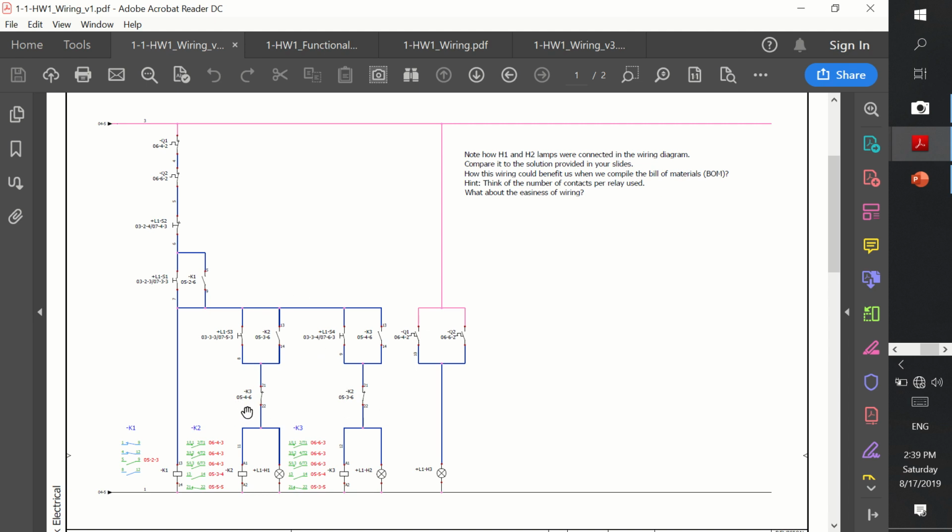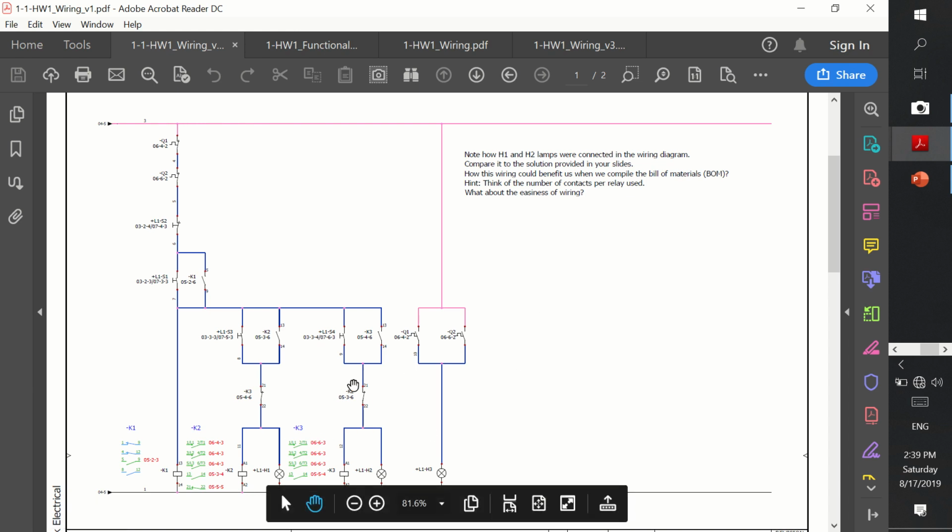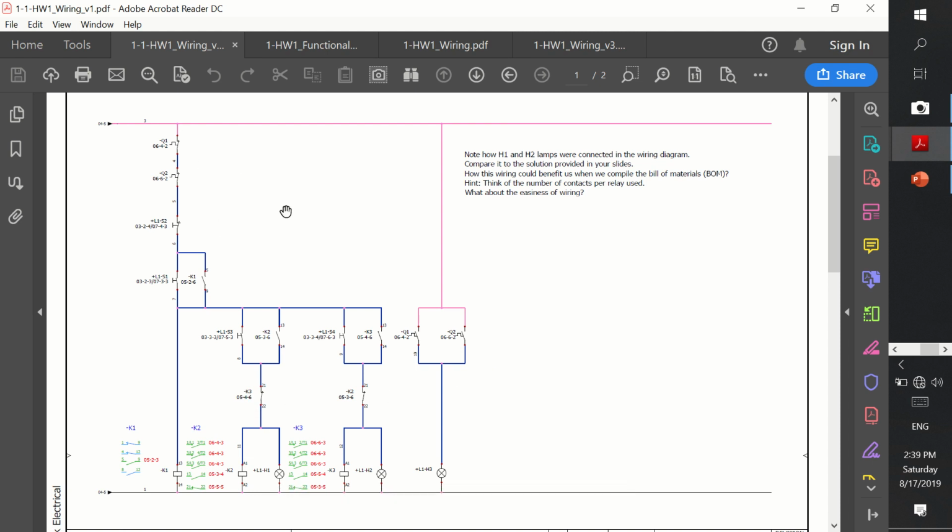And now we are assuming that the K2, K3 will actually be sufficient to operate the power contactors, since we are assuming we are dealing with 24 volt operated power contactors. Now, once I tried to assemble the RLC circuit shown in part 1, I was faced with the problem of insufficient resources. So I have to reconsider the whole circuit and redesign it from scratch in order to accommodate the available resources, where I have actually 2 power contactors that are operating using 220 volt AC instead of 24 volt DC, and I have to reconsider that.